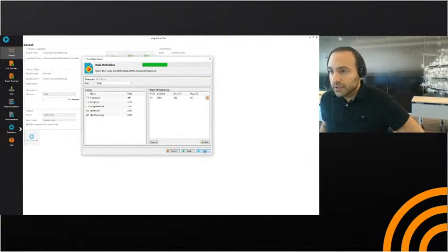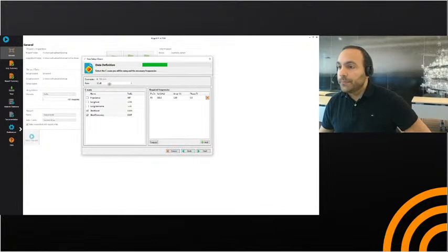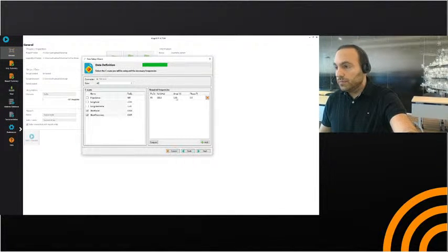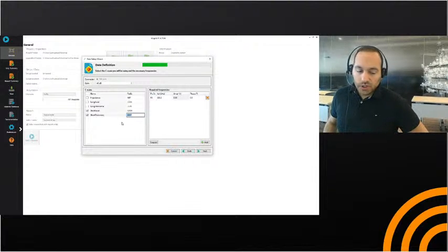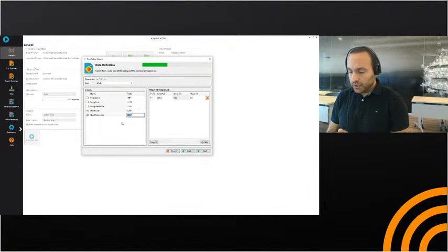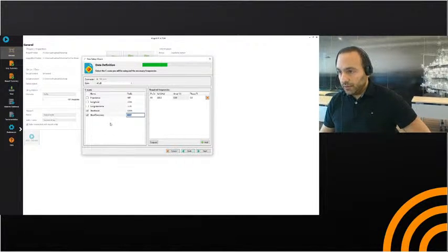Next, here is the data definition. Here you can adjust your hardware gain. You can add the frequencies. You can put the amplitude needed. And here you select the configuration needed for your scan. I will start with these values, 5 and 8, and I will be choosing the short double driver topology. This topology or configuration is best suited for my application. To detect really small cracks, I will need to use this configuration.